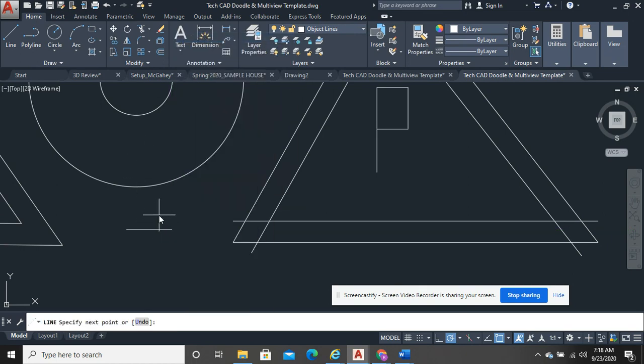I think your trim button looks like that. Is it like a forward slash or a backslash or something else? Mine looks like scissors. Or if you hit TR spacebar, that's also going to pull up trim. That's the fastest way to do it, and you use trim constantly. You'll use it all the time.